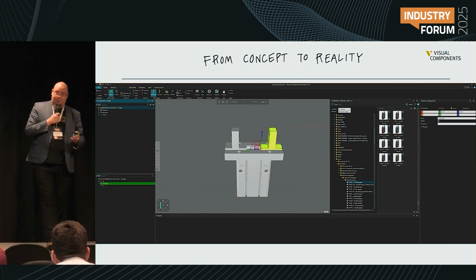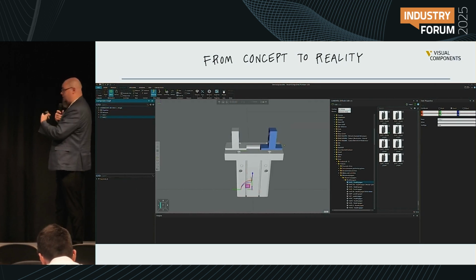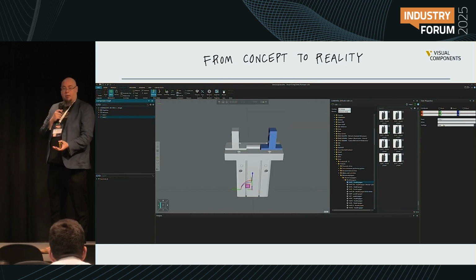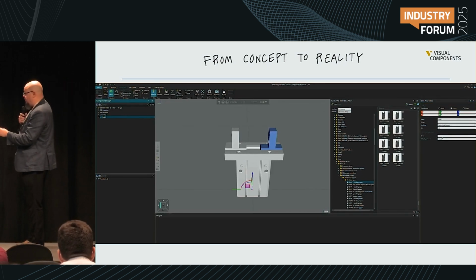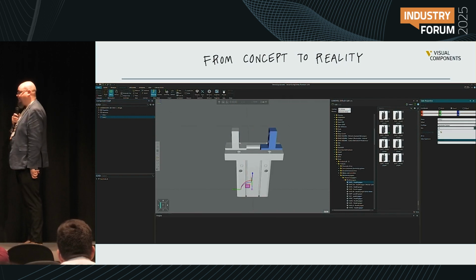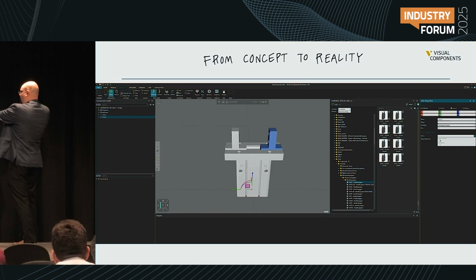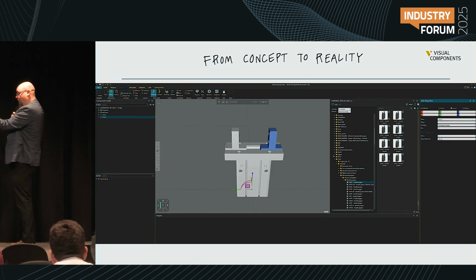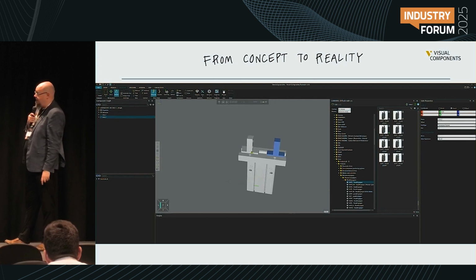And again, this information is something that you need to dig in from the Festo's page. But if the component itself would know it automatically, for example, in any format, we could of course read it automatically here. But now we created a finger, and of course the other side is the follower of the first movement. And now we have our gripper with the moving fingers.